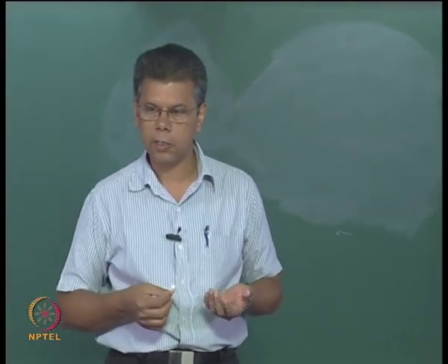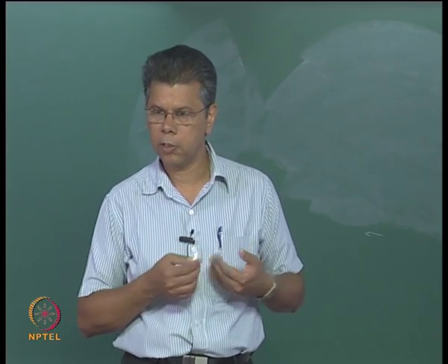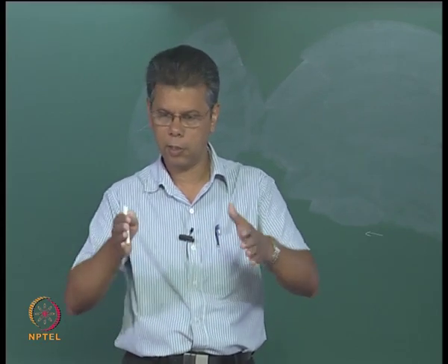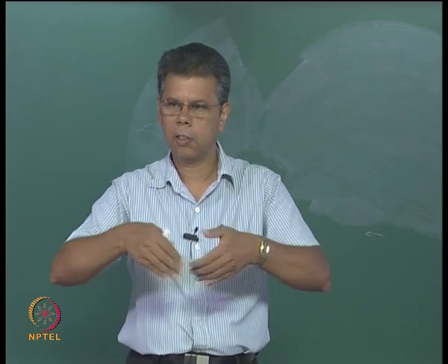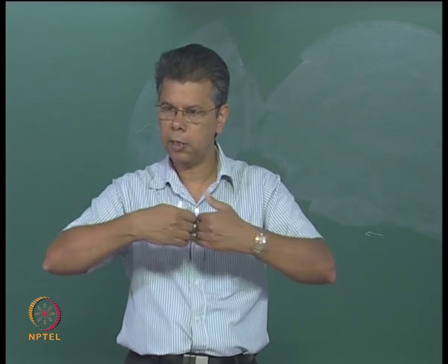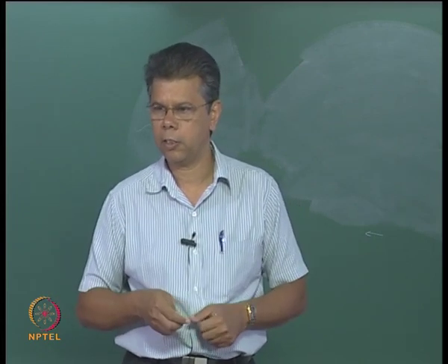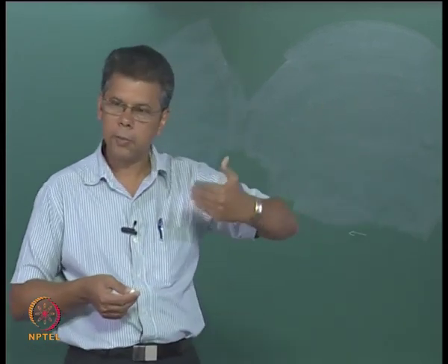The flow velocity increases. It is obvious, you must have noticed that when there is a channel, when there is a reduction in the section, the flow increases. The law of continuity should be maintained, so the velocity increases. Same thing here, the flow velocity under the ship increases.